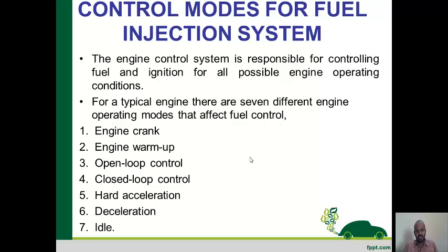So these are the 7 different operating modes in an engine control, or you can say engine fuel injection controller, and there is no necessity that it has to follow this sequence. For example, here it is mentioned that idling is the last mode, but it is not necessary that idling has to be last. Even sometimes after engine crank, idling mode will come. So based on these 7 different operating modes, the engine fuel injection system will be controlled with the help of the ECU.